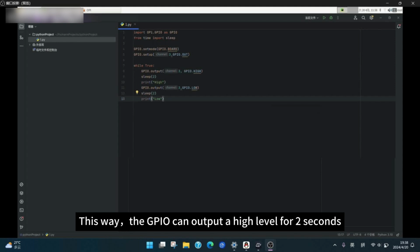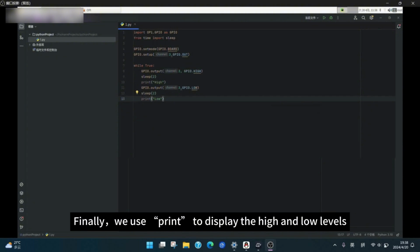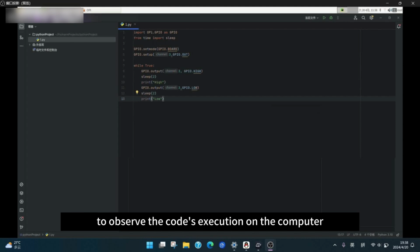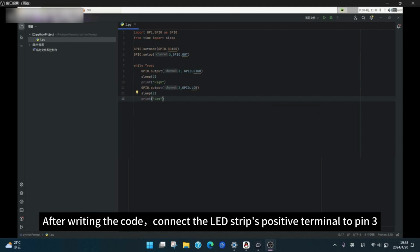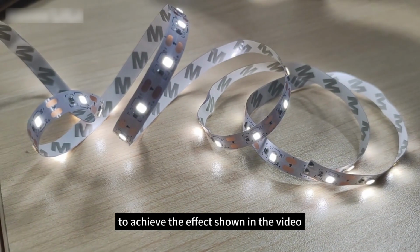This way, the GPIO can output a high level for 2 seconds, and then output a low level for 2 seconds. Finally, we use print to display the high and low levels, to observe the code's execution on the computer. After writing the code, connect the LED strip's positive terminal to pin 3, and the negative terminal to GND. Once wired, click the Run button to achieve the effect shown in the video.